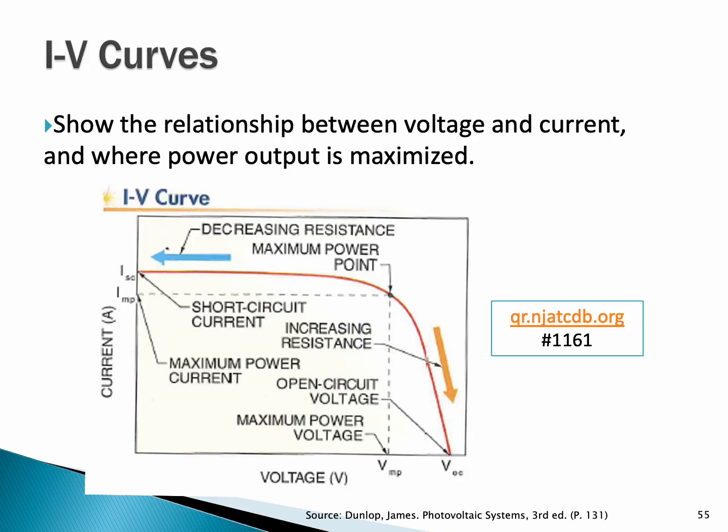And so then the inverter would apply more voltage, or allow more voltage into the system, so that we would be operating on this curve, further down the curve, but at its maximum power point for that given condition. This is also called the knee of the curve. Those are terms that you need to be familiar with for the exam that comes up at the end of the semester.